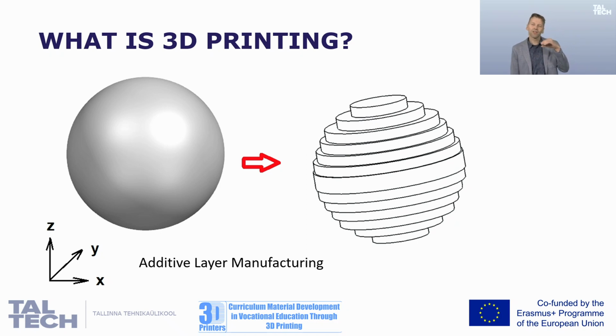These layers are two-dimensional, which means that there will be stair steps between the layers, so there will be small inaccuracy. But when the layer thickness is small enough, this stair-stepping effect is not that important anymore.